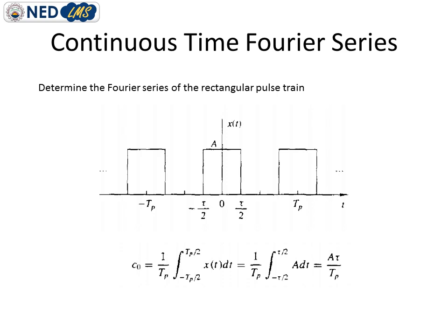Now first you have to look at the nature of the waveform, and you comment that this waveform is continuous and periodic. So we can use the continuous time Fourier series analysis equation to determine its spectral components, and we are using the exponential form of that Fourier series.